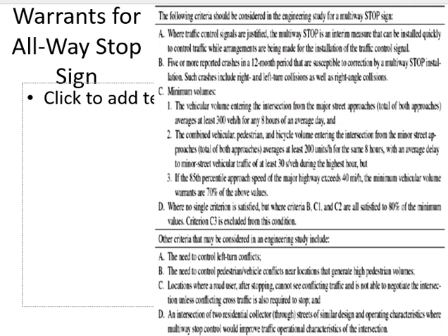Combined volume for the minor road. Combined meaning vehicles, pedestrians, and bicyclists. All three of them combined. For the minor road it is 200 at least, again for the same 8 hours of the day. So for example, if the volume on the major road remains 300 or more from 12 to 8, then on the minor road it should remain 200 or more for the same 8 hours, 12 to 8.